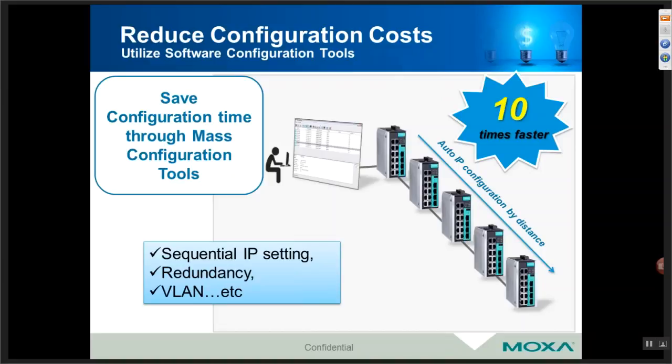But when we talk to most of our customers that are control engineers or not necessarily IT experts, they prefer a user interface that's a little more graphical. A lot of them don't realize that many of the manufacturers offer a configuration tool that allows them to configure multiple devices from a single PC, often saving up to 10 times the amount of time it takes to commission a network.